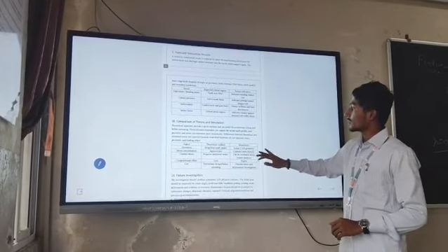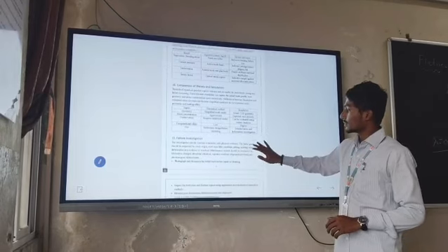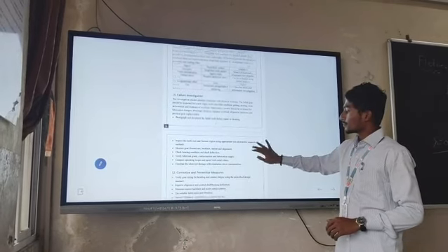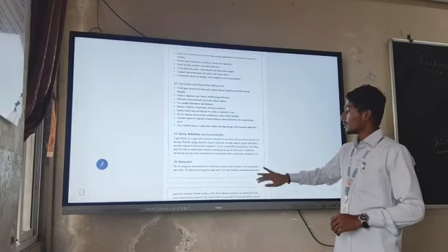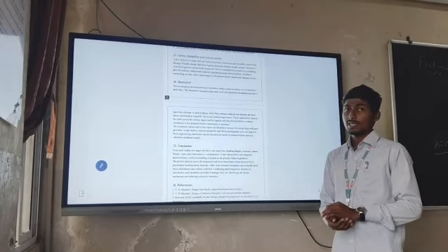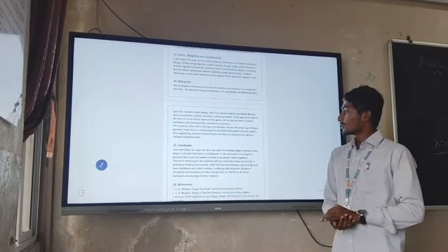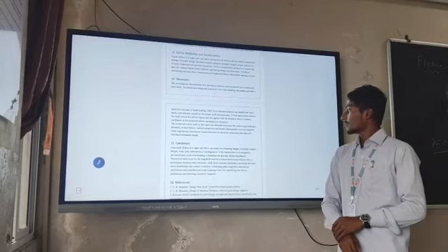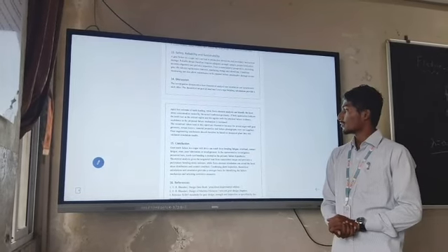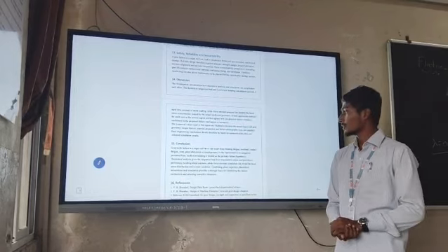Next are comparison of theory and simulation, then fatigue investigation, safety and reliability, and sustainability. From this we conclude that gear tooth failure in a sugar mill drive can result from bending fatigue, overload, contact fatigue, wear, poor lubrication, or misalignment.